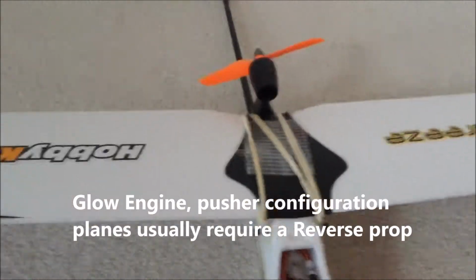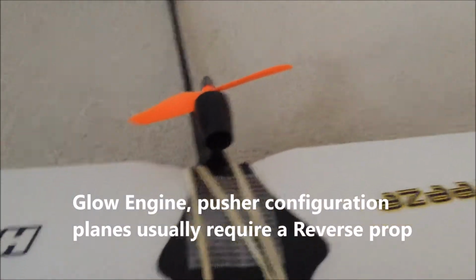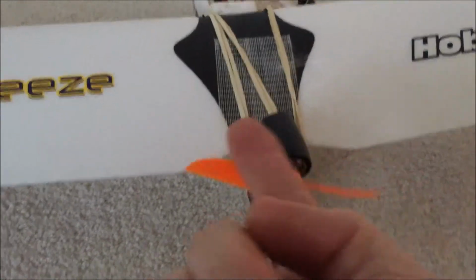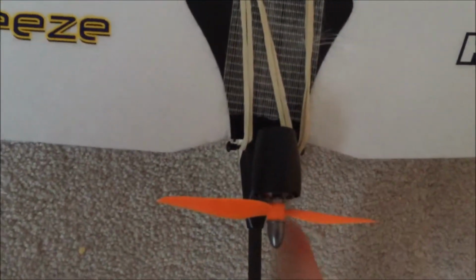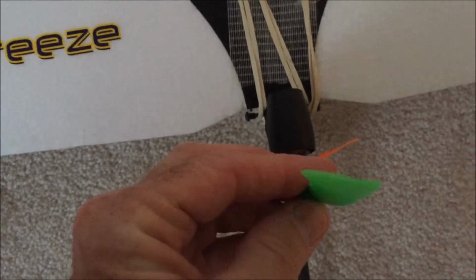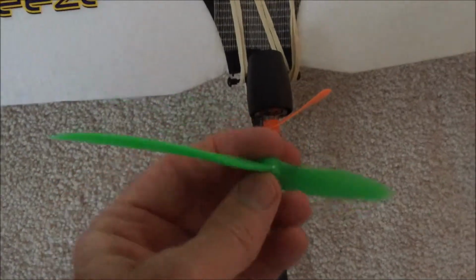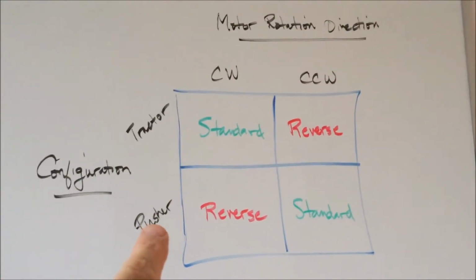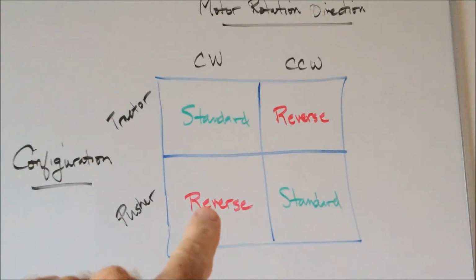In the days before electric RC airplanes, when glow engines were the only game in town, you were stuck pretty much with a glow engine that was going to rotate clockwise. From the rear, that meant that the prop was going to be rotating counterclockwise. So in that case, you were not able to get away with a standard prop, and you needed what's called a reverse prop. This is a reverse prop, called a reverse or counterclockwise or left-hand prop. So what that meant was, in a pusher configuration with a clockwise rotating motor, you need a reverse prop.